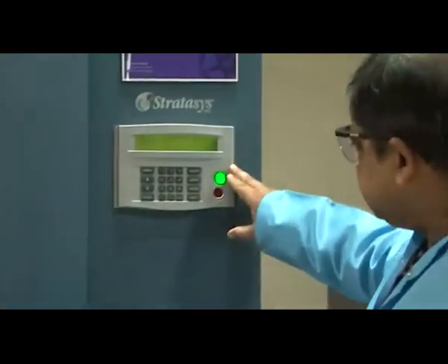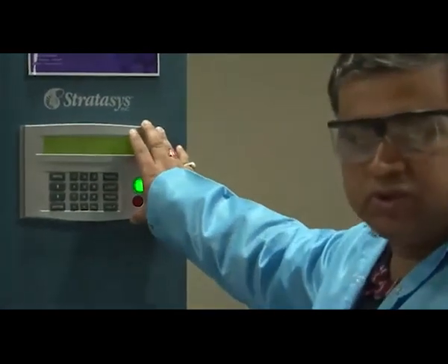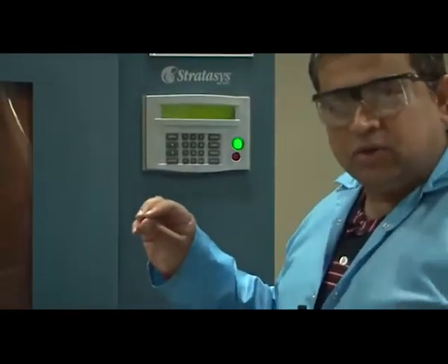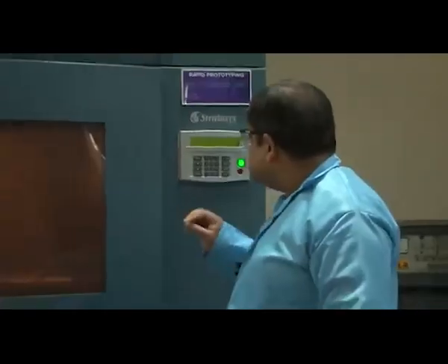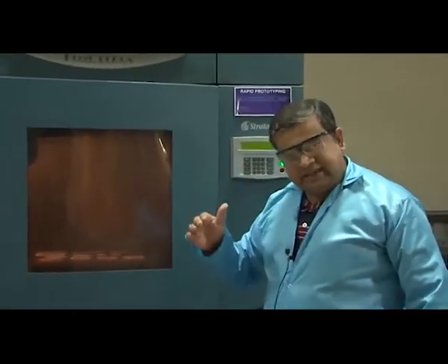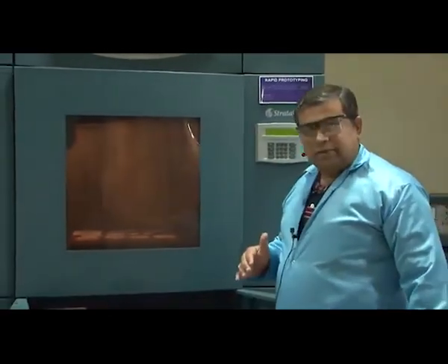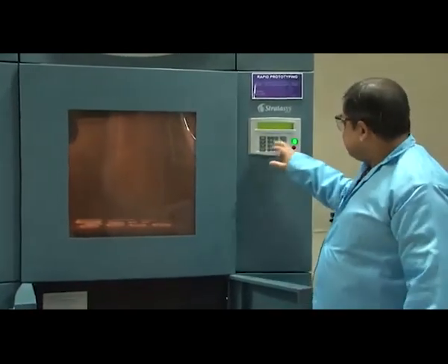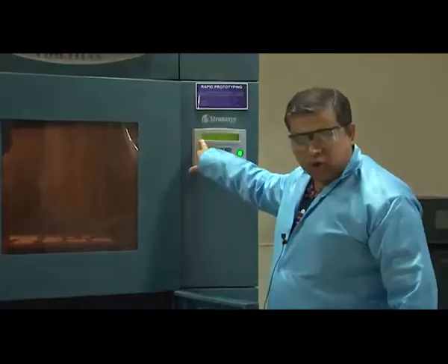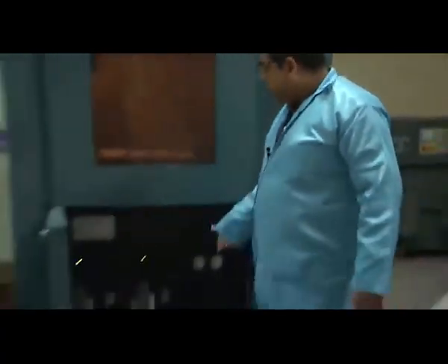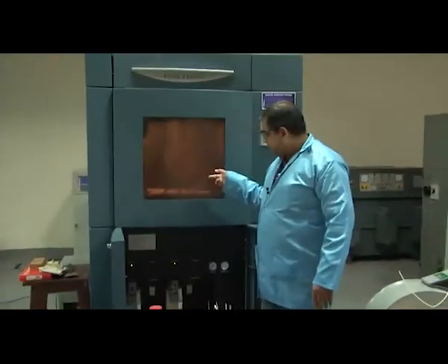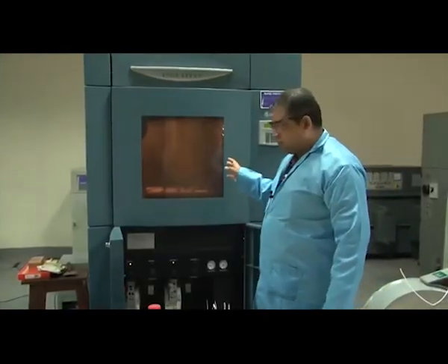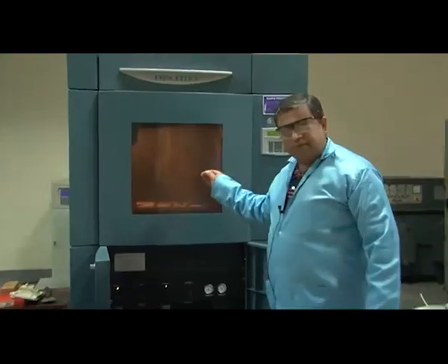There are several processes which are happening here after the controller has been switched on, and one of them is basically to auto home or auto position the dispenser unit or nozzle in the XYZ plane. It also does several checks and balances at the beginning so that the machine can be completely initialized for the next run. So we'll have to wait a little bit until the cursor here comes to unlock door, and at that point we can open the door. You see the light has been turned on inside the chamber where the rapid prototyping can happen. The first stage of this machine would be related to setting up of this machine.